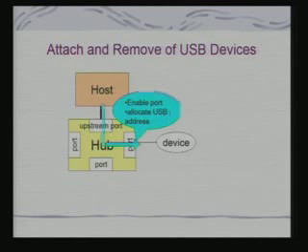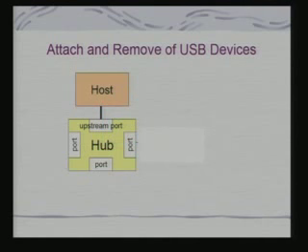Now what does the host do? It enables the port, allocates a USB address to the device, and also identifies the device driver which is required for the device. If the device is removed, the port actually gets disabled, and the host removes the indicator, and the host therefore can sense automatically whether the device is removed or not.